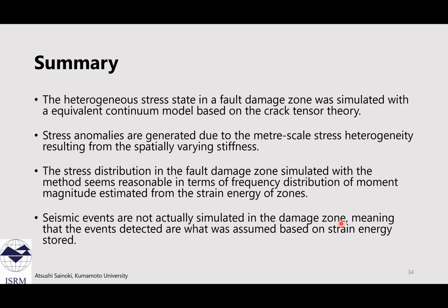So here is a summary. The heterogeneous stress state in the fault zone was simulated with an equivalent continuum model based on the crack tensor theory, and the stress anomalies are generated due to the major scale stress heterogeneity resulting from the asperity, and resulting from the spatially varying stiffness.